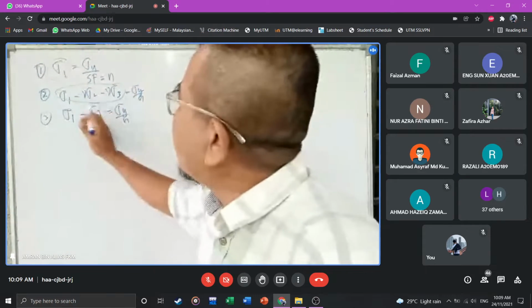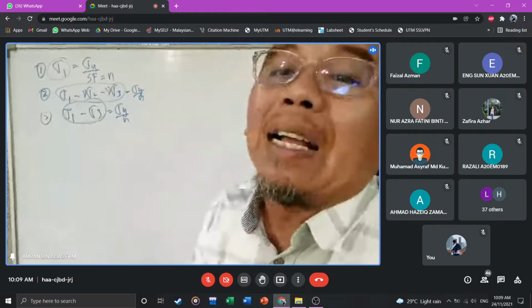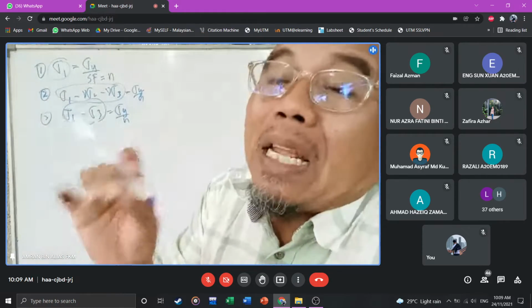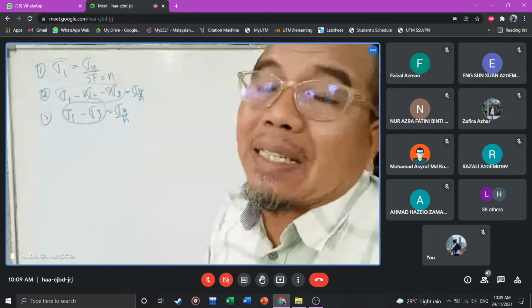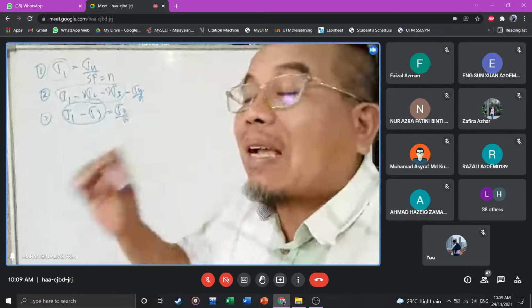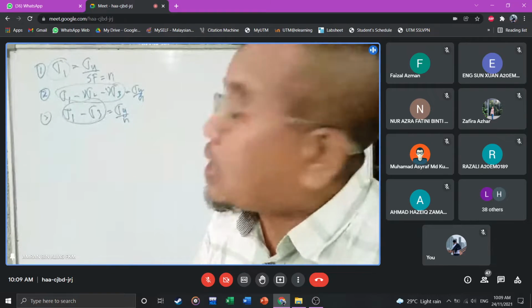So what do you call sigma 1 minus sigma 3 here? The formula is Tresca. Sigma 1 minus sigma 3 is the meaning of Tresca stress. This is Tresca stress compared to sigma y. So the Tresca stress must be lower than sigma y in order for it to be safe.